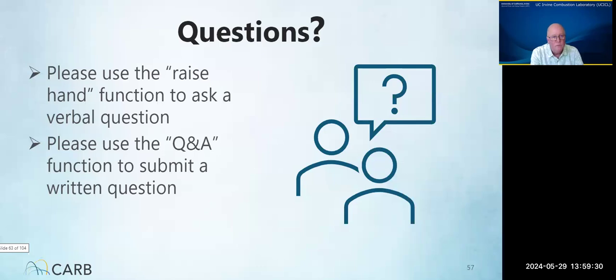Additionally, CARB's verification procedure has an engine pre-installation compatibility assessment that needs to be completed before any CARB verified DPF could be installed on a particular engine family, to ensure that it's compatible with that engine family and that the DPF in its installed configuration will not exceed the applicable engine OEM's maximum allowable specification for back pressure.